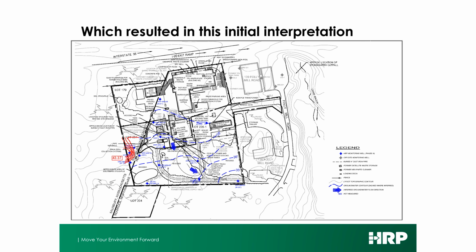Well, this is a sand aquifer that goes on for miles. There's no way, short of having a pumping well right there, to get the water table to either draw down 6 feet or come up 6 feet. And the person who drew this should have known that right off the bat. But these are the kind of oddities that you really need to pay attention to. This one is very easy.